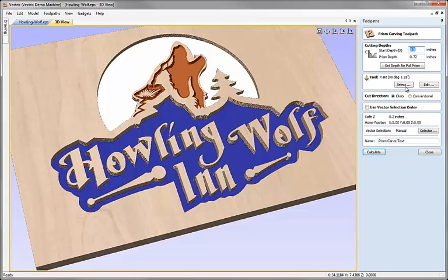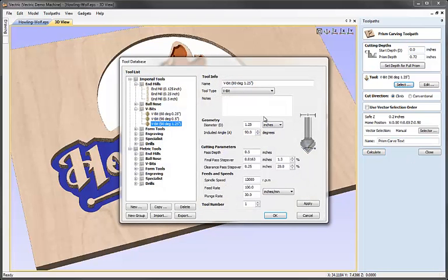And then what I could do is come up and select a different tool. Now it may be that I have a 120-degree V-bit that I could use, so we could add this to the tool database here. I can take the one which we've got there, make a copy, and then change this to 120 degrees, also remembering to update the name there, very important. The rest of the parameters look okay there, and pass depth may be a little deep,